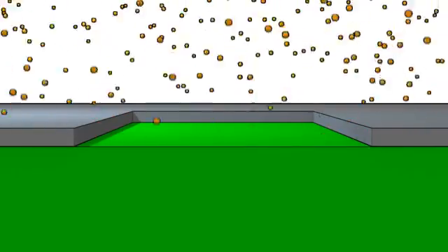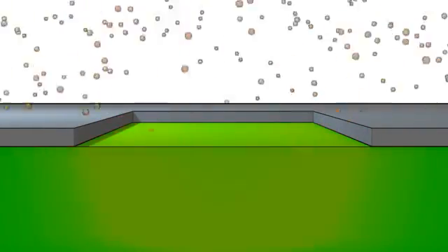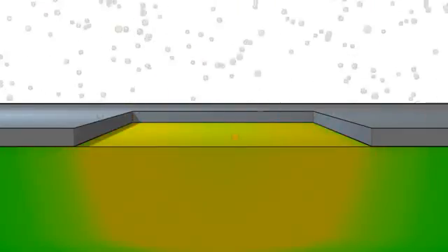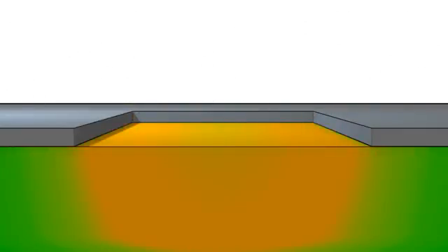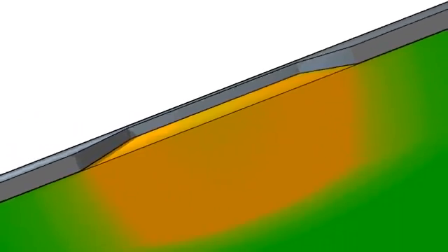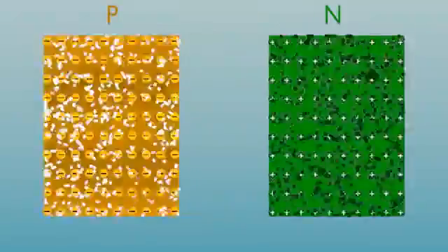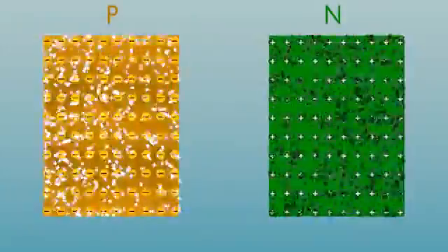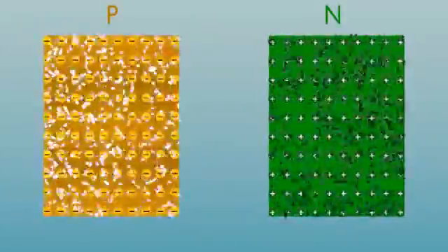The process of fabricating a p-n junction begins with an n-type or p-type doped semiconductor, into which the opposite type of impurity is introduced. To understand how this structure works and what physical processes take place in it, a didactic model is used. The model consists of a p semiconductor perfectly matched to an n semiconductor. The p semiconductor has a much higher hole concentration than the n semiconductor.